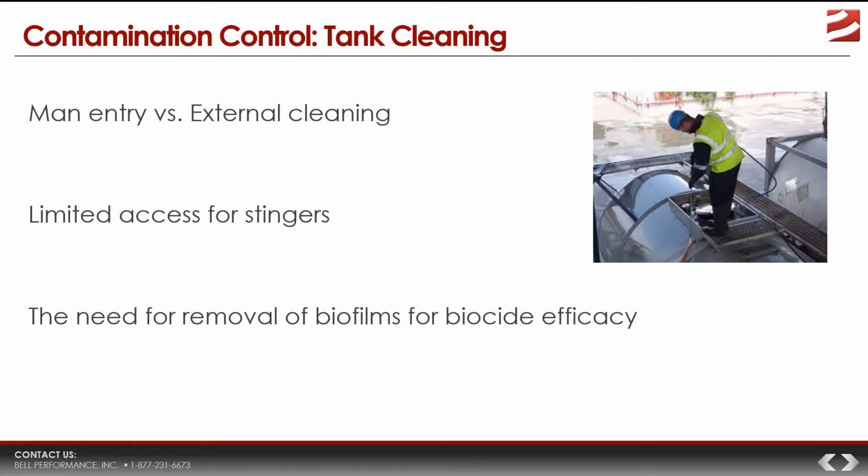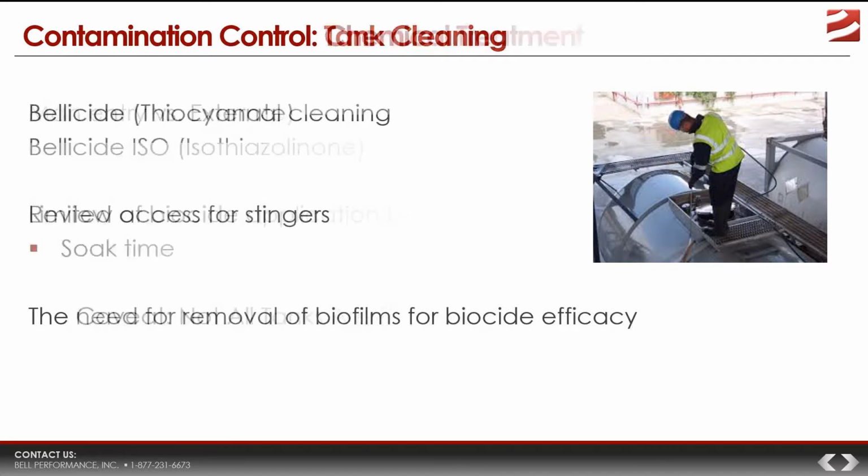And one reason why tank cleaning is important in this context, too, is if you're going to use biocide, many biocides can only penetrate a certain way down into the biomass. If there's a lot of biofilm left, if you didn't get all of it, well, depending on how much you leave behind, it increases the chances that the biocide treatment that you're going to follow up with may not be as fully effective as you might want it to be.